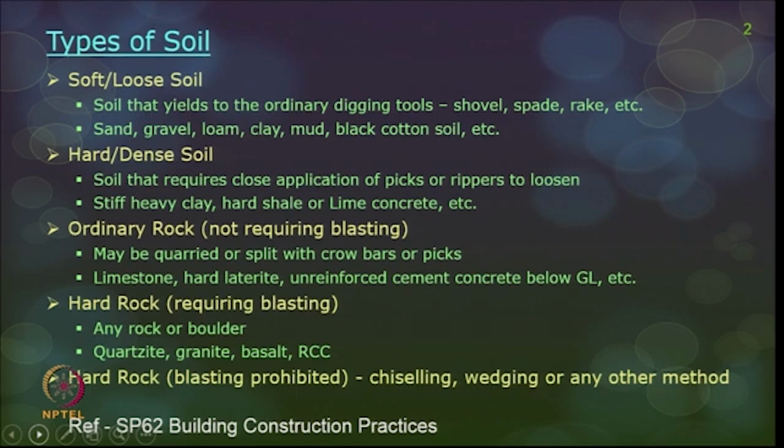The next type of soil is hard or dense soil. Examples are stiff heavy clay, hard shale or lime concrete. You have to apply more energy and force, and so you may have to use rippers or something similar, because you have to work closely and loosen the soil so that you can take off the earth.